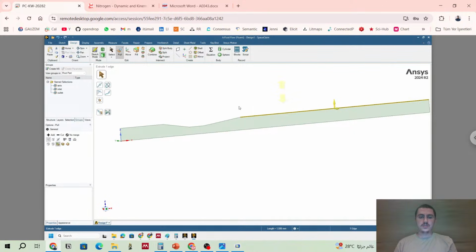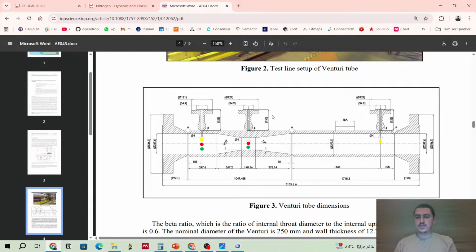Then I click on this, Control click, I keep clicking on the edges. I want to define these edges. Do you see that they are like walls here, where the fluid cannot pass? Because of the adhesive forces, the liquid which is the neighbor of the solid surface will have no slip, will stick on the surface, zero velocity.